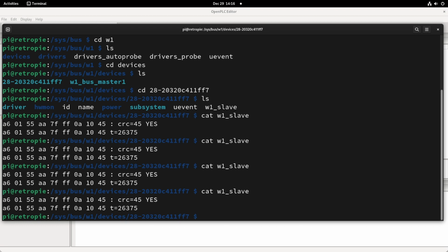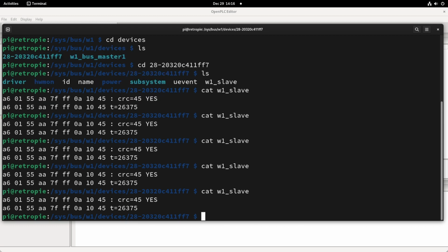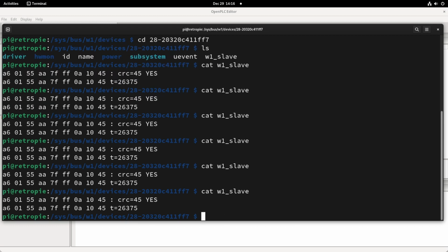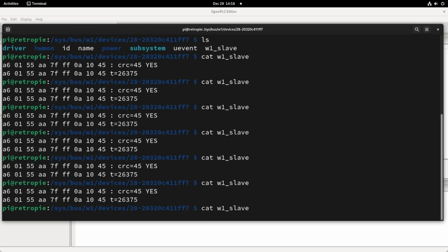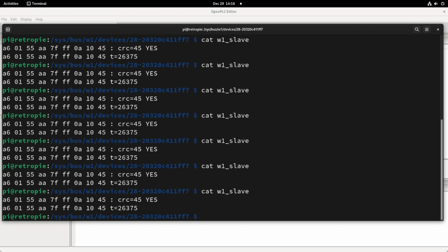But we must be wise when we're programming drivers to make sure that slow measurements are not affecting other measurements that we're making on that driver, right? So we're going to discuss this once we start writing our driver on PSM. But just keep in mind that this is a slow measurement. You see, it takes about 1 or 2 seconds to give me back a temperature measurement.